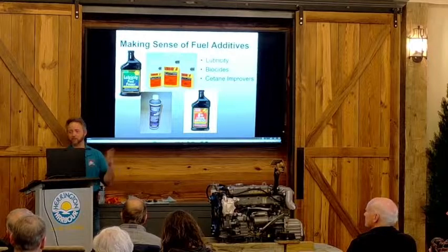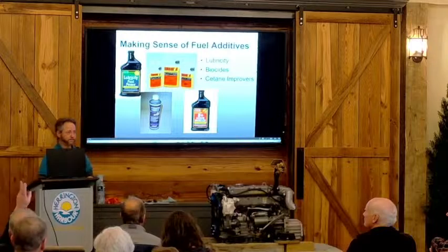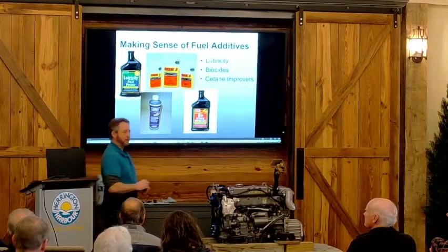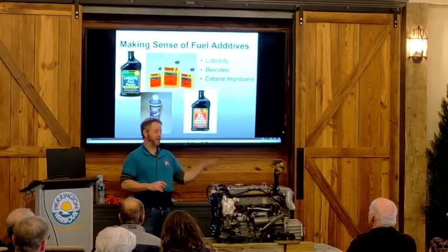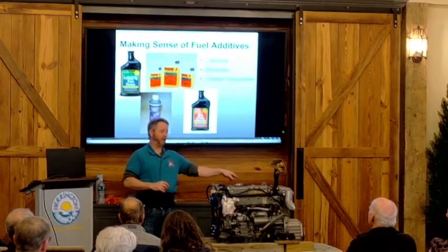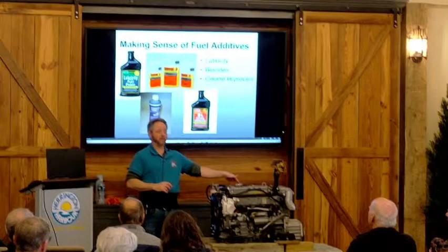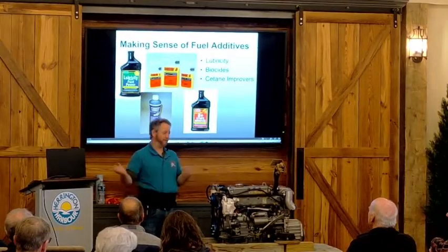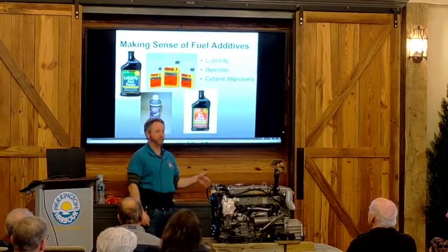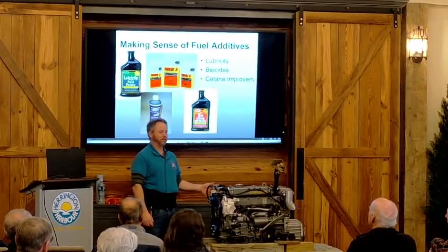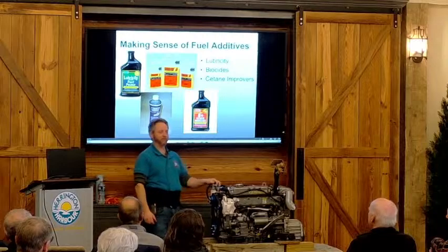But for my customers, we just do it all. We do all the filters in the fall. On most fuel filters, it's a couple hundred hours, a couple hundred hours on your secondary. The primary is going to be done with the oil, 100 to 150 hours. But I just do them all because it's actually easier to bleed the fuel system when the secondary's been changed too. You get better results.